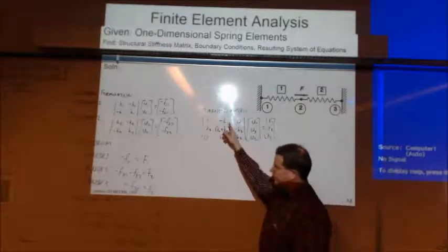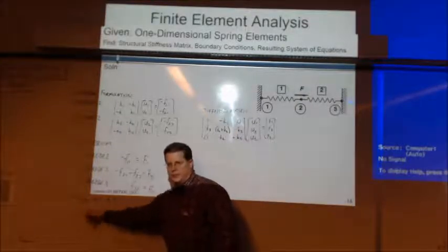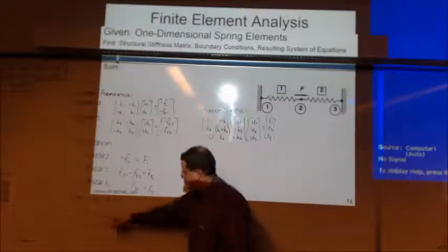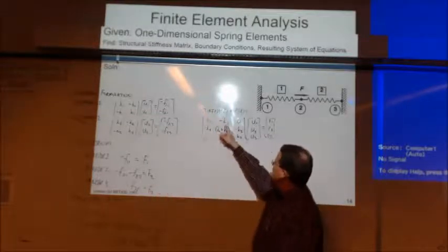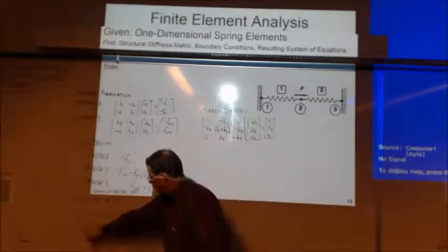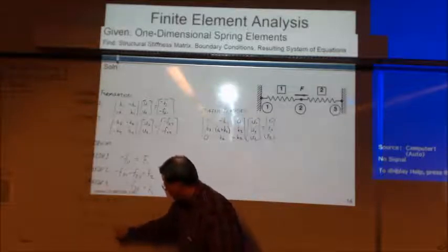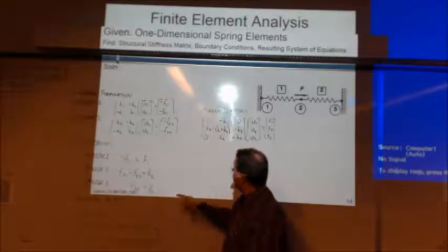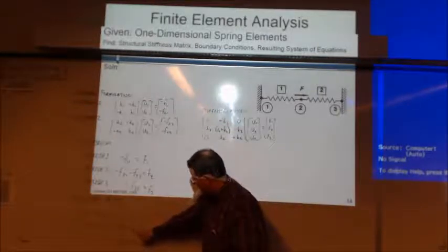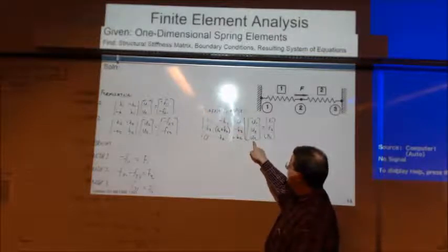Okay, so is this making sense? Right? I have K1s in this position. And I have a minus K1 and then 0. We have a minus K1 to U1. I have 2 Ks for U2, so K1 plus K2. And I have a minus K2 for U3, right, because this is going to multiply to here, right?